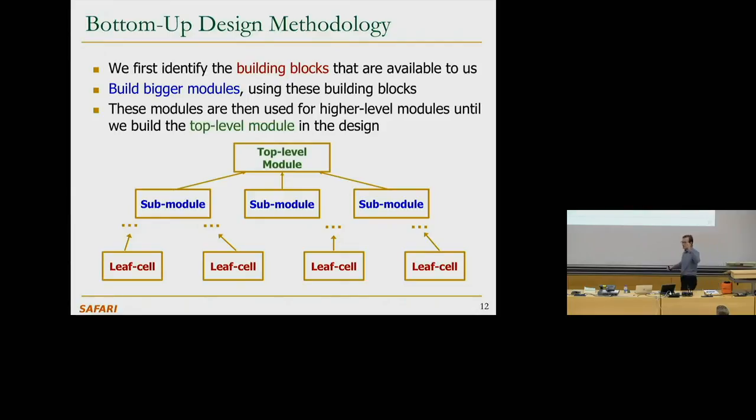So usually, top-down and bottom-up meet. Usually, you start with a top-level design module, and then you break it down into pieces. And then you also usually have some libraries at the bottom. We'll see there are some basic functions that are provided by Verilog, but you could build libraries on top of that, and then you could meet in the middle and design your modules.